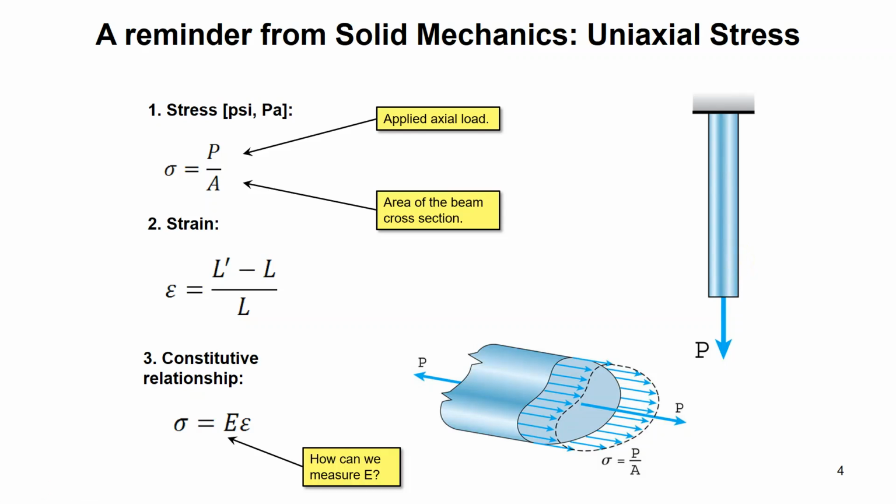Right? So this is the basic of design. Never make a stress more than the capacity of the material. Never make it more than strength. Right? That's the basic. So now, how would you exactly mathematically define a stress? We define a stress to be the force divided by the area. So if force P is divided by an area where the section area is A, then P divided by A is called a stress. Clearly, the unit for that is Newton per meter squared, which is called Pascal, or pound force per inch squared, which is PSI.